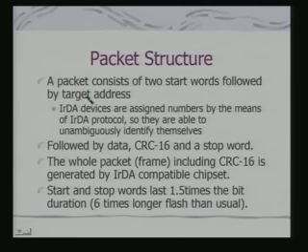So, what we really have in this case is a definition of a packet or a packet structure. A packet consists of two start words followed by the target address. IRDA devices are assigned numbers by means of the IRDA protocol, so they are able to unambiguously identify themselves. This property is similar to that of your USB as well as IEEE 1394, because here also I can just plug in a device, just bring a device near to a receiver and then they can start really communicating with each other.